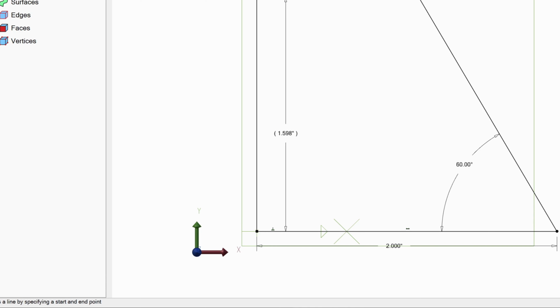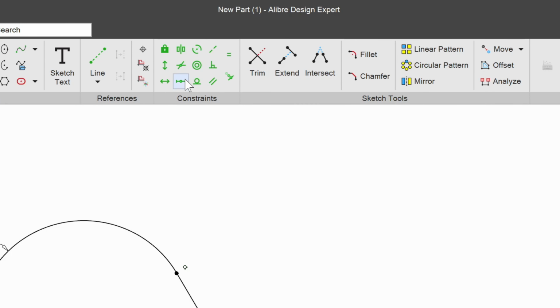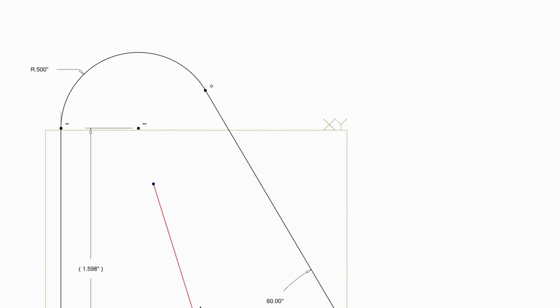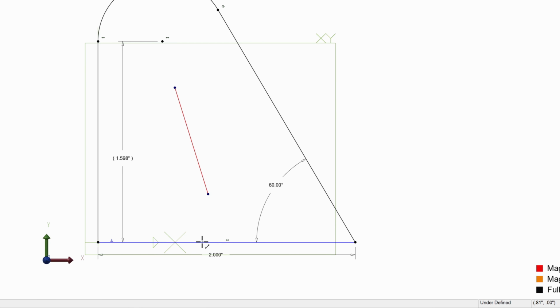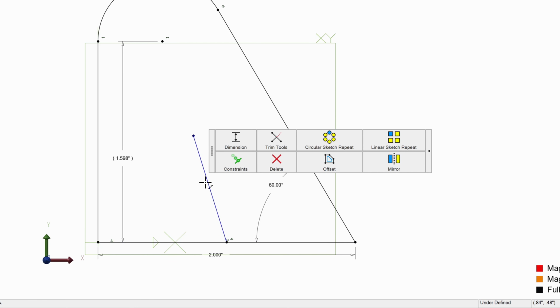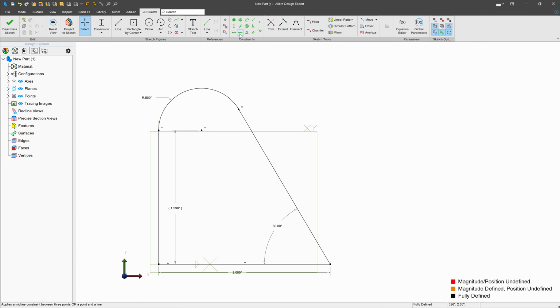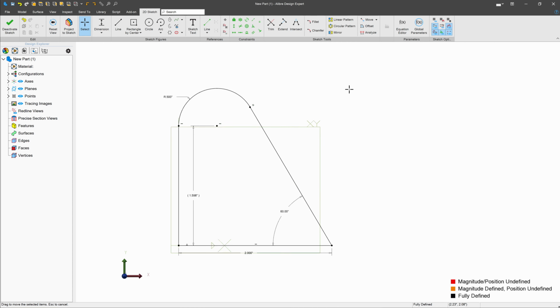But if I have a line, and after the fact I want to connect it to the midpoint, that's not showing up. So what I can do is choose this midline constraint, and I can say I want this point to be on the midpoint of this line that I'm about to click, and it snaps right onto that midline, no problem. So that's the midpoint constraint. Interestingly enough, I can choose a line, and I can choose the midpoint of an arc as well. So don't forget that arcs can have midpoints, and you can use that when making your lines. Perhaps I want things to be symmetric.